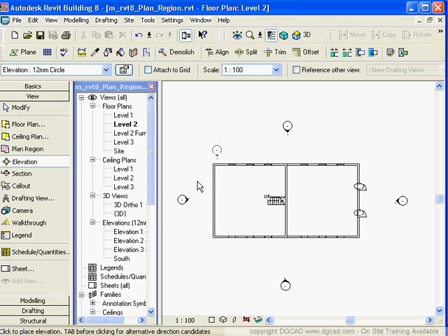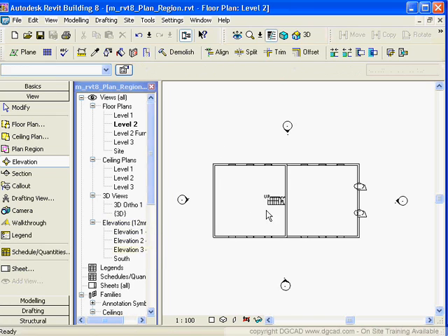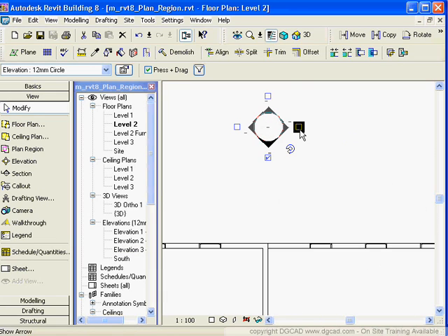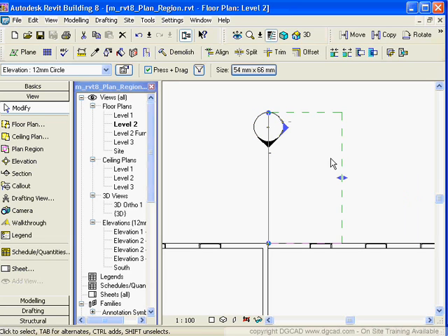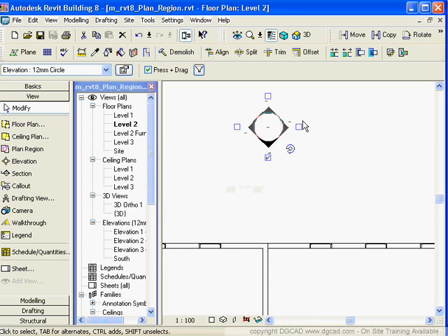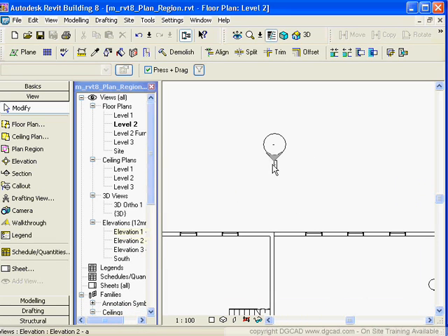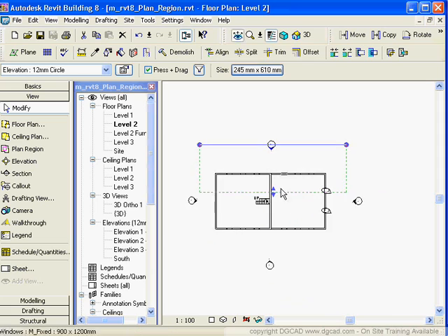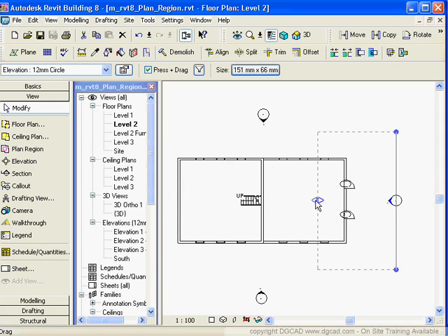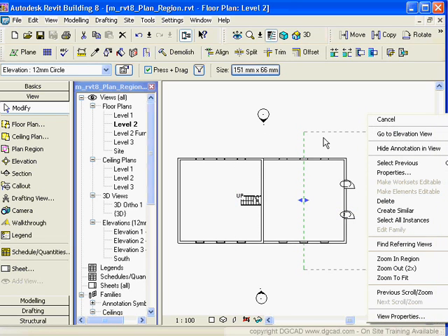So it's very smart, these objects. As you place them, it's putting them in, and you can see it's populating these elevations down in here. So really there's the elevation here, and if you check mark on here, then it'll create an elevation looking that way. Clicking on the bubble takes it back, and then it erases that elevational view as you do that. When you click on the tip of the elevation, it gives you a different aspect, and then it tells you here what it will encompass when it does its elevational view.